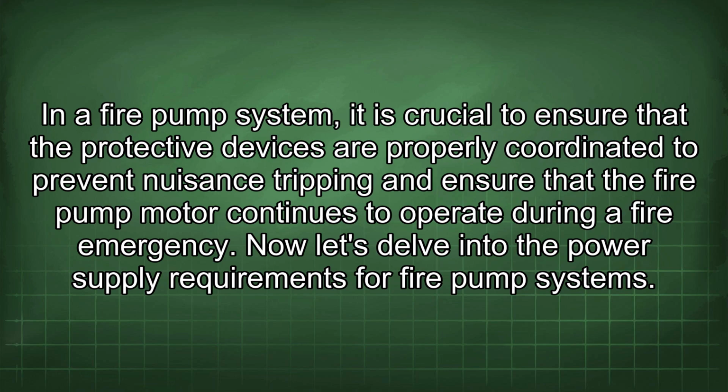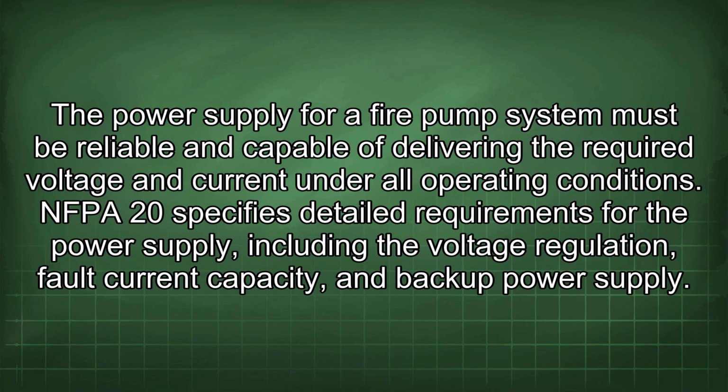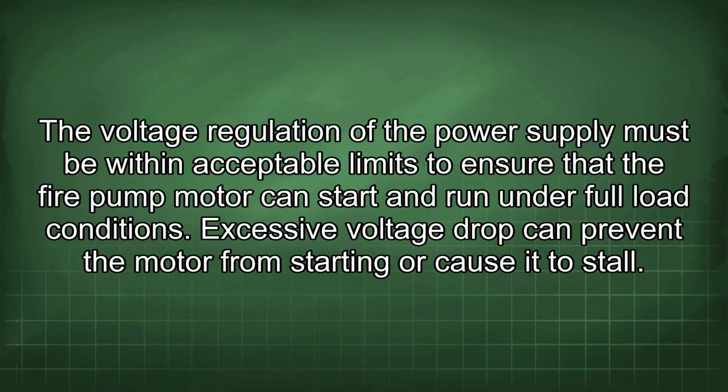Now let's delve into the power supply requirements for fire pump systems. The power supply for a fire pump system must be reliable and capable of delivering the required voltage and current under all operating conditions. NFPA 20 specifies detailed requirements for the power supply, including the voltage regulation, fault current capacity, and backup power supply. The voltage regulation of the power supply must be within acceptable limits to ensure that the fire pump motor can start and run under full load conditions. Excessive voltage drop can prevent the motor from starting or cause it to stall.